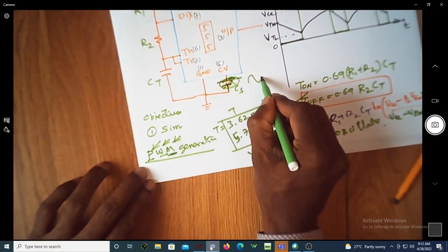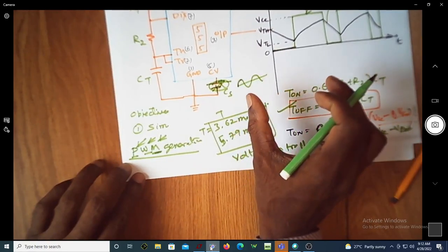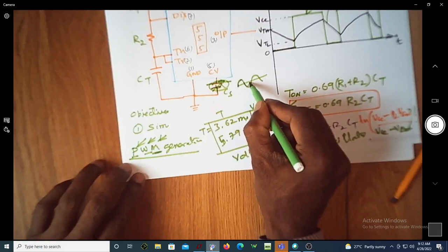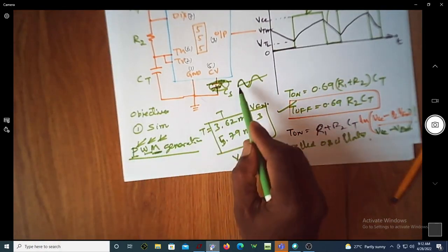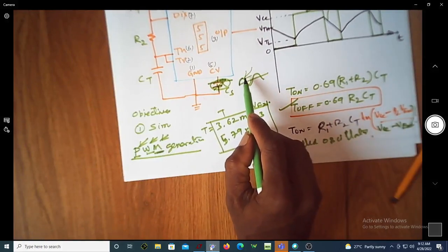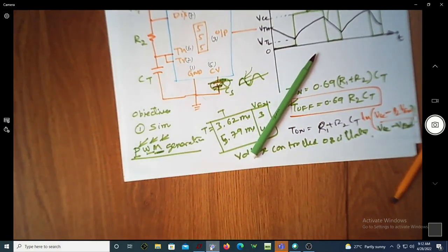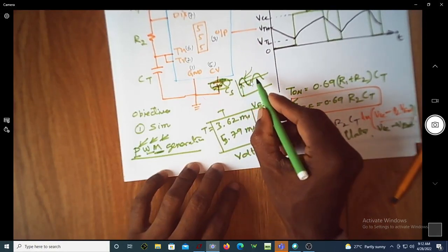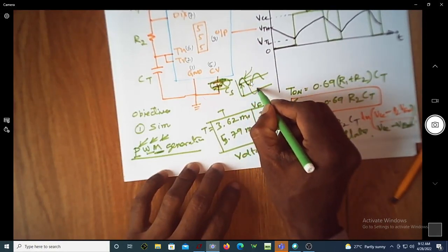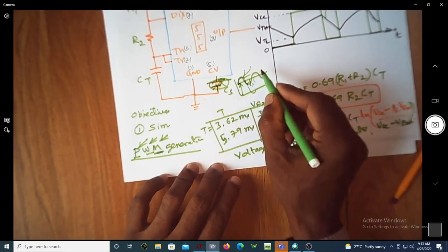So this is a sine wave here. As the sine wave amplitude keeps on increasing, the width is increasing. As the sine wave amplitude keeps on reducing, the width is reducing. So that's why there is a width variation happening depending on the message, depending on the sine wave. Only constraint is that this sine wave should have some DC shift, and this should not go below 0, and this has to have a bit lower frequency.